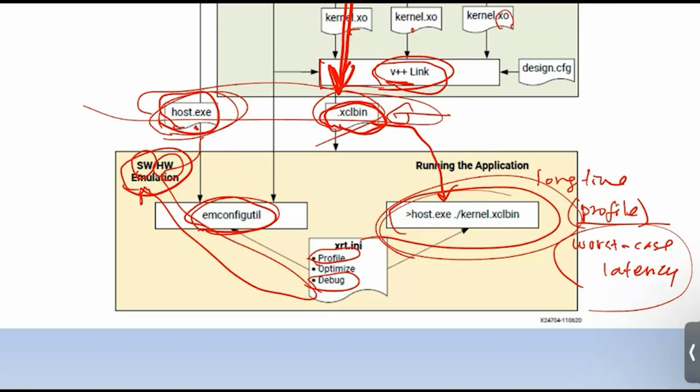Yeah. And also a good design I will recommend if you are really doing product development: you have to do the burn-in. In the burn-in process, you have to put pressure on the system, and you also have to turn on the profile. The profile gives you insight into the timing data, and in the timing data, you probably need to draw a histogram.